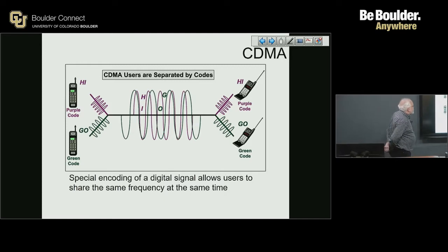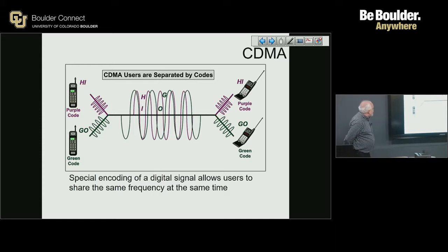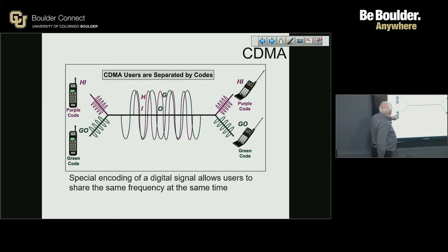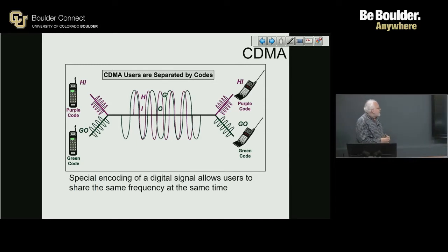One that's relatively new compared to those, although it's actually getting quite old now, is CDMA. It was developed back in the 60s. And we could argue that frequency hopping code division multiple access actually predates that. But the idea behind code division multiple access is by taking two different signals and encoding them orthogonally using two different orthogonal coding sequences, I can put them on the same medium and then at the other side separate them out. This seems like magic, and it kind of is, because to some extent you can get something for nothing out of a CDMA system.